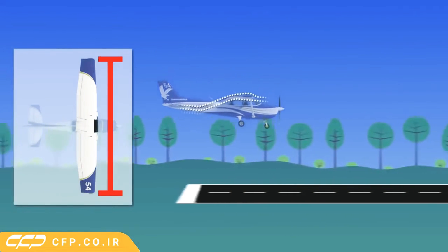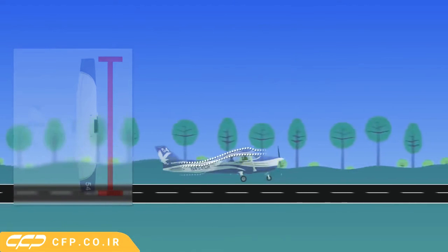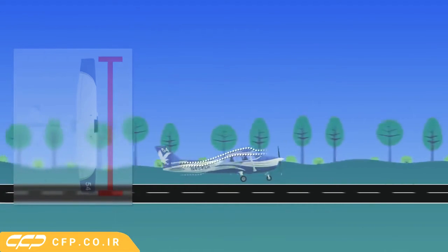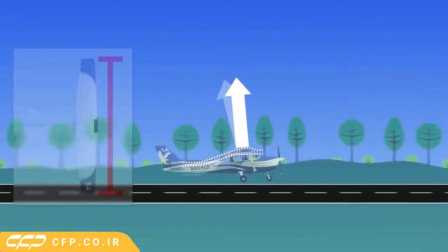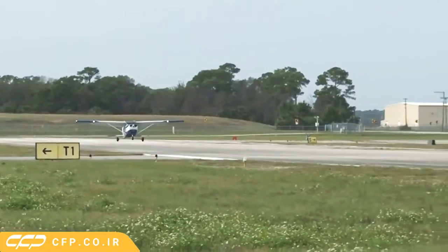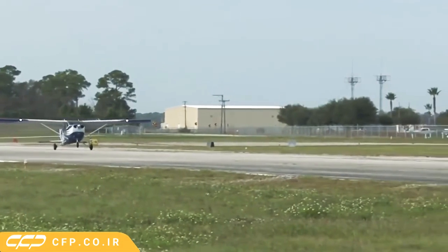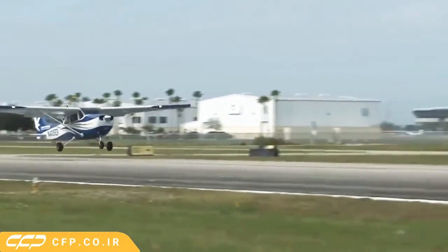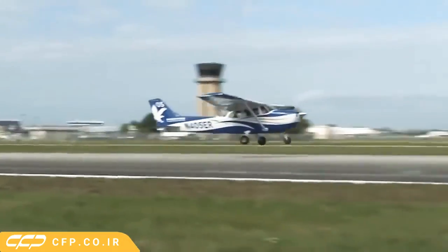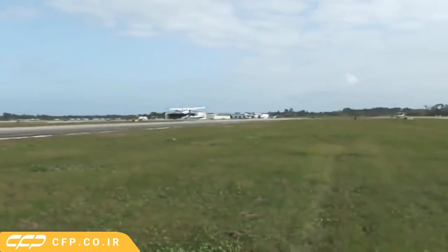Flying within a wingspan of the ground itself changes the downwash of the air flowing over the wings. This shifts the lift vector forward and reduces the amount of induced drag. Pilots can take advantage of ground effect when performing a soft field takeoff. This lets the airplane lift off the ground before the regular liftoff speed. However, they'll need to hover over the ground for a few seconds to increase their speed before they can continue to climb out.